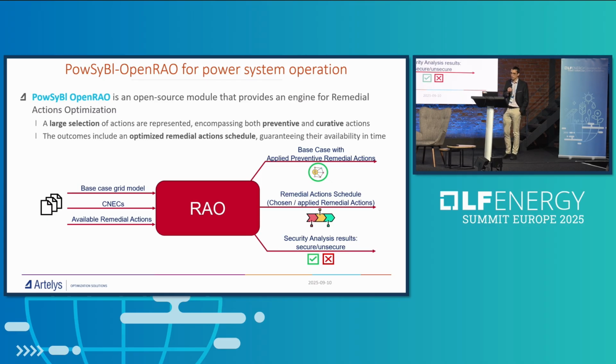So in this case, you run the remedial action optimizer that takes all the nodal constraints into consideration and finds the optimal way to address them by applying non-costly actions, that is topological switching, or changing the set point of PST or HVDC lines. And then when it cannot be done with only non-costly actions, it does counter trading or redispatching, trying to minimize the costs.